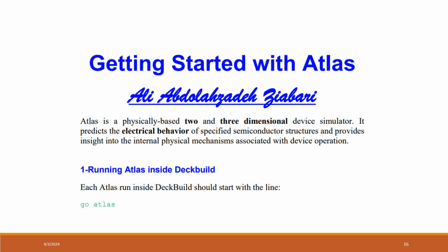After the theory part, I will give you one code of a basic TFET, an SOI TFET you can say, and I will simulate that code on Atlas also. I will show you the result in current form as well as in structure format. So let's begin.